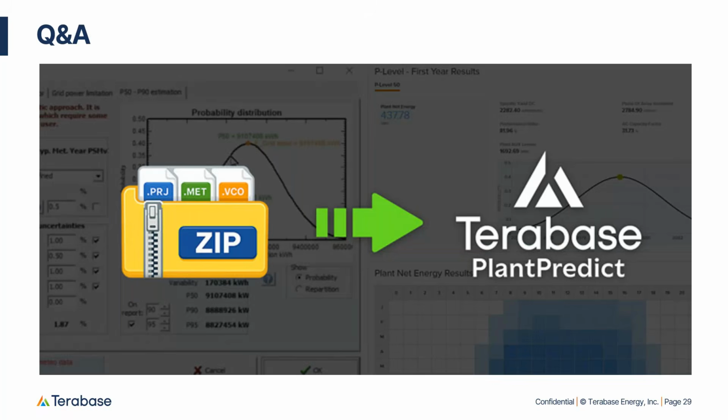First question: does PlantPredict support the latest PVsyst version 8.1.5? Yes, actually the demo that I gave today was using 8.1.5. We've primarily tested the import process with version 8. We have done quite a bit of testing in version 7 as well. We have not tested import before version 7, so be aware of that.